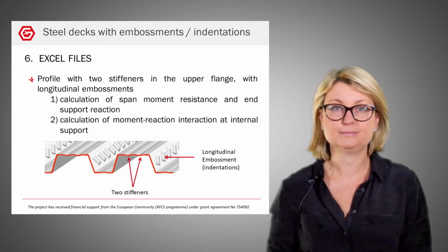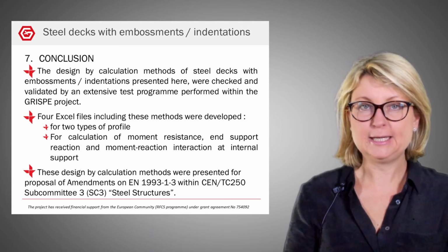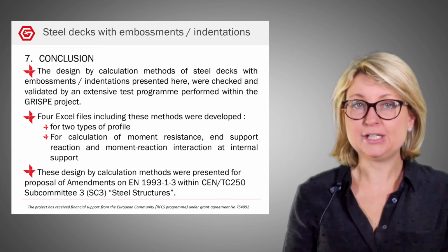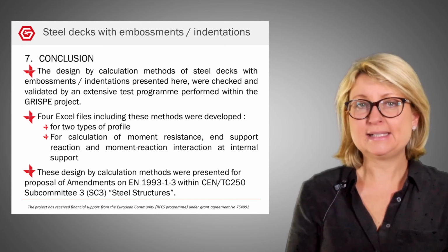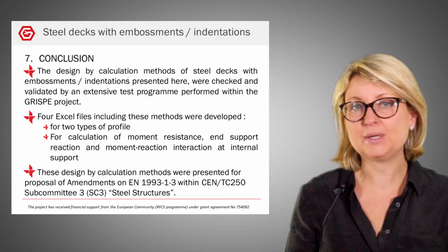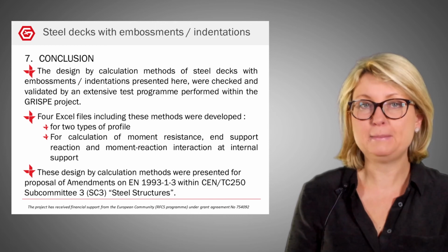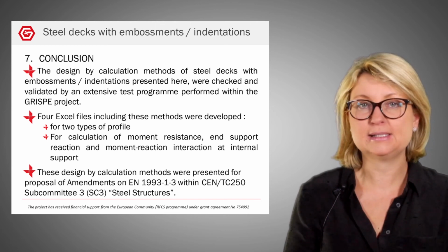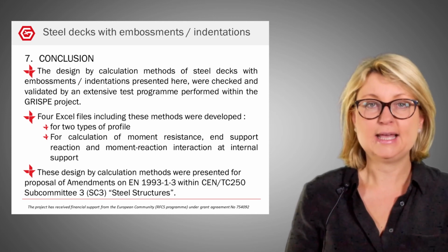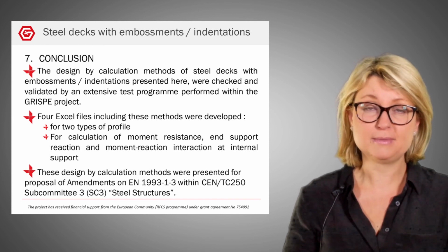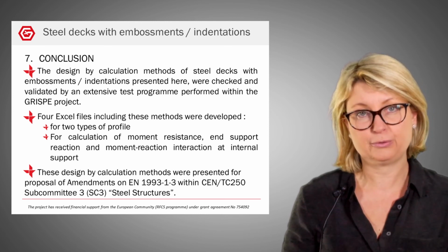To conclude, it is important to underline the following points. Firstly, these design by calculation methods were supported, checked and validated by an extensive testing program performed within the GRISP project. Secondly, 4 Excel files were implemented to calculate the resistances of a profile with embossments and indentations. And lastly, these calculation methods were proposed for amendment on Eurocode 3 1-3.